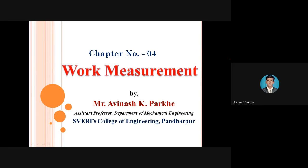This work measurement concept is mostly implemented in the industry, because whatever operations we are performing, by using the concept of method study, I have eliminated all the unnecessary operations. But for the standard operations that we are performing, we have to go for the measurement of the time. If I am performing drilling, facing, turning, chamfering, so many operations, for each and every operation we have to go for the time measurement. If I measure the time of each and every operation, then I can calculate the total standard time required to convert that raw material into the finished goods.